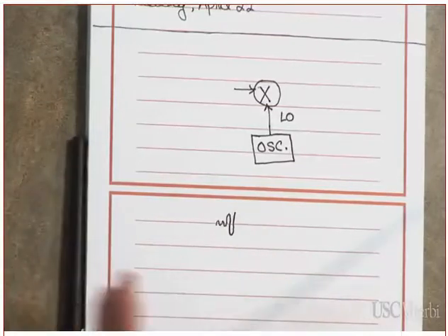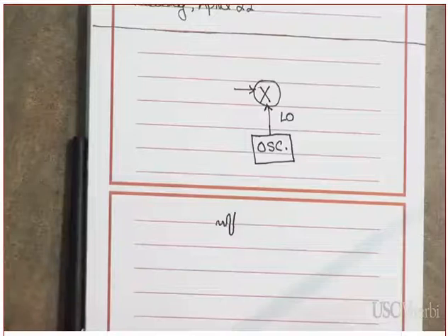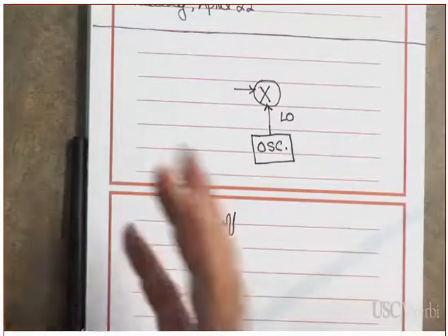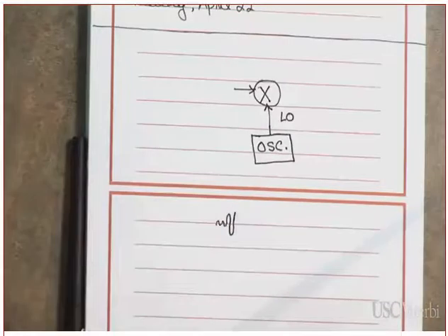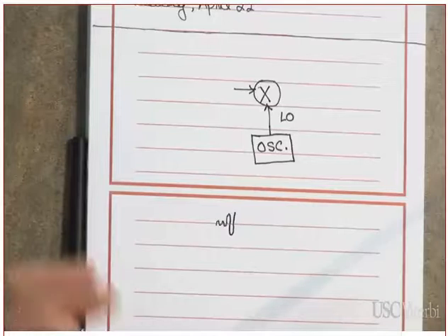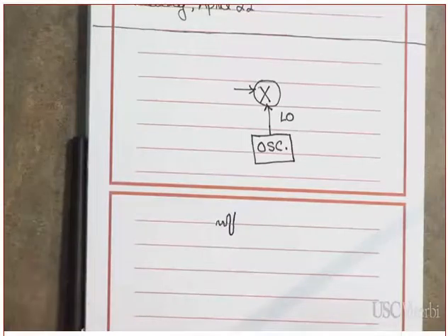The point that I'm trying to make is that an oscillator cannot be designed as a passive circuit. It must have amplification in the circuit to build this oscillation until you reach the right amplitude, and then it needs to sustain it. So the design of an oscillator always involves an amplifier. An amplifier is part of the design of the oscillator.